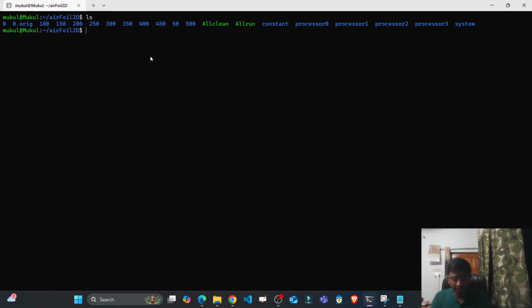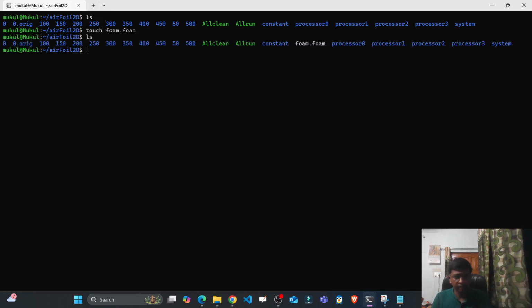After that, we will first make a touch foam.foam file, and then we will just run paraview.exe foam.foam.